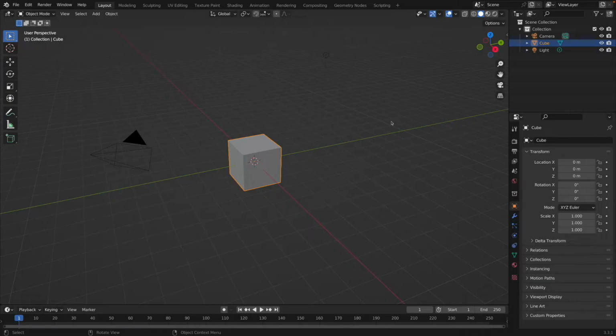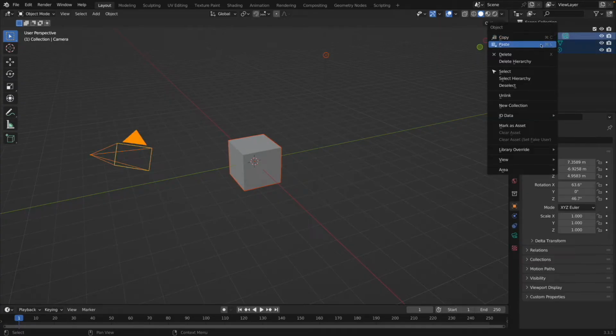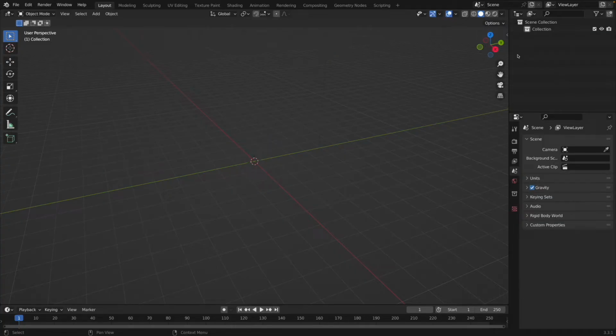Once we are all set, that is, once we have installed Blender and its two add-ons, we can start importing real-world geometries using OpenStreetMap. We'll import a small part of the city of Paris in this case. We start by removing these three objects that Blender adds by default to the scene. To do that, let's go here on this view, select the three items, do a right click, and then click on delete.